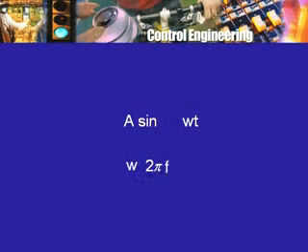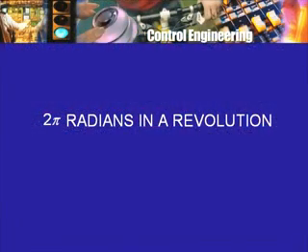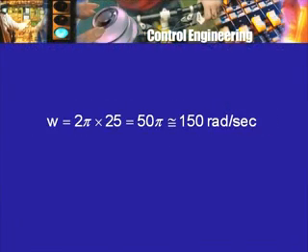So this omega, although it is the frequency almost, not quite f, is 2 pi f, where f is the frequency in hertz. This omega will be what? 1500 rpm corresponds to 25 revolutions per second. So omega will be 2 pi times that, and therefore omega will be nearly 50 pi. Omega, the angular speed in radians per second, is 50 pi.